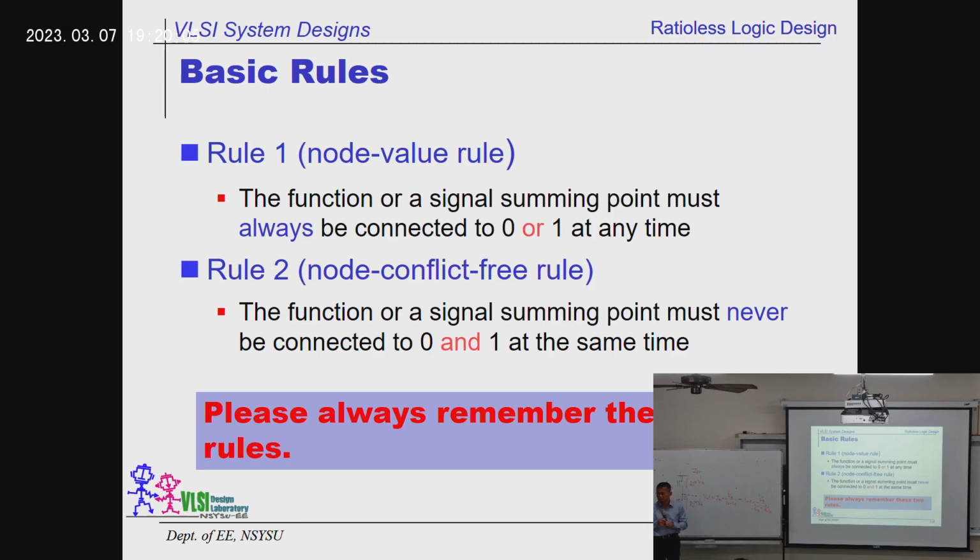Now we have a very funny story. What is that funny story? Look at these numbers here. The output voltage could be very high. How do we do that? If RB is much, much larger than RA, then this term can be ignored, so the output will be very, very close to VDD. You know what I'm saying, right? And on the contrary, it can be very close to the ground.